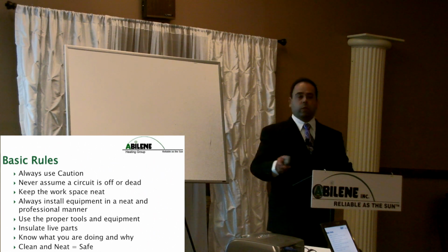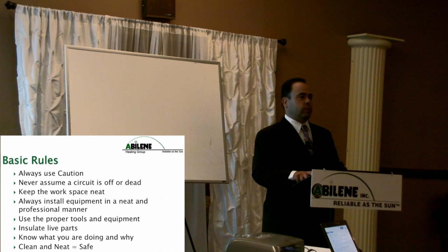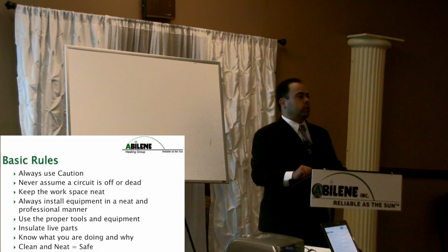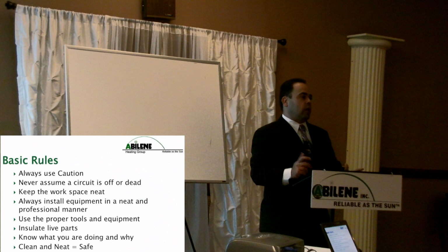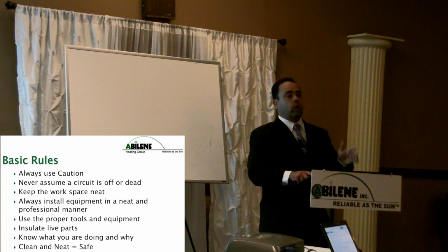Use the proper tools and equipment. That says it for itself, right? You want to use the proper tools. You're not going to use uninsulated lineman pliers, right? You're not going to use an uninsulated screwdriver in a panel, right? You're not going to use just the end of a knife to lock down a screw, because if it shorts out, it's going to burn you. All right? Use the tools required.